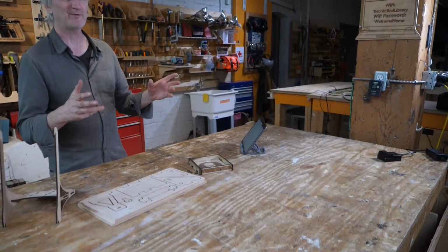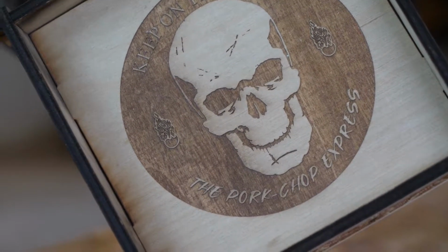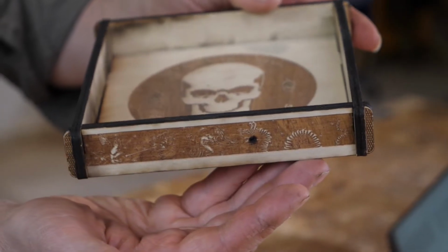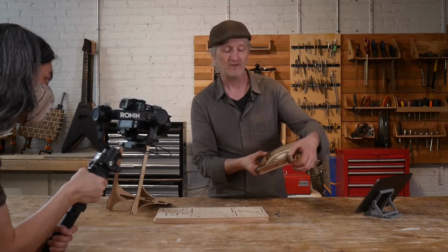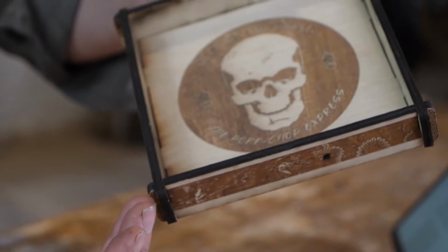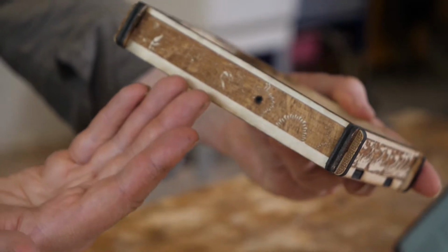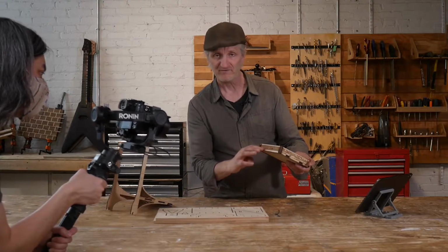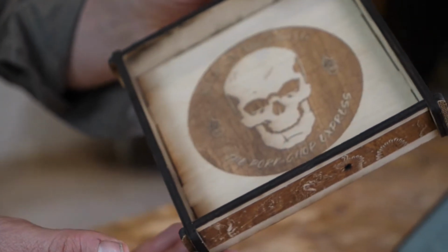So let's talk about the way that CAD organizes things. If we take a look at this cool dice tray that we've got right here, CAD would consider this entire thing to be a part. Now that part would be composed of individual bodies. These can be the same or they can be different from each other. And every body would be described by sketches that provide us the outline of the part. And then that sketch would be composed of individual features that describe things like these little cutouts for the tabs and the slots that we've been working on.